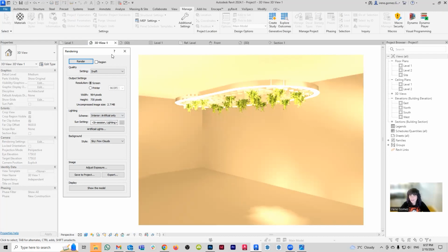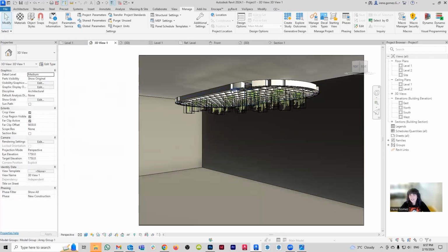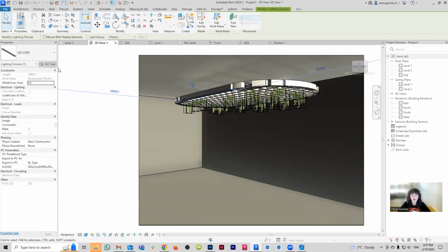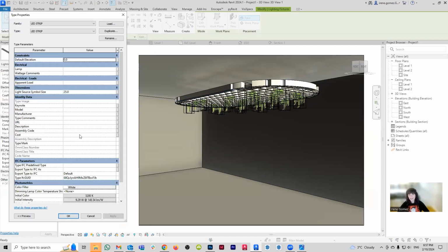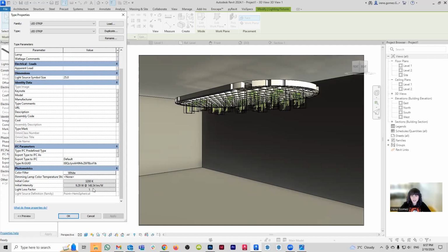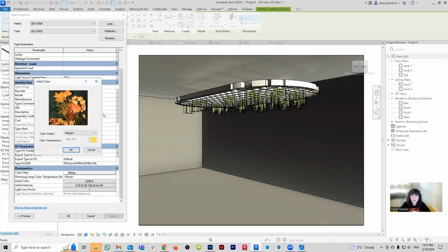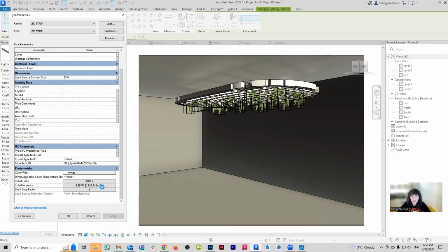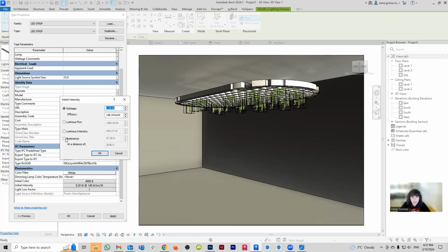Okay, we need to adjust our light, which is the reason that I like to work with linking the properties, because now I can control all of the LED properties through this single dial. So I can come here and, for example, say that it was too yellow. So maybe instead of 3,200, I want it to be something like 4,000. And then the most important, now it's going to take a while because remember, there's a lot of them right here. And then I'm going to change the intensity.